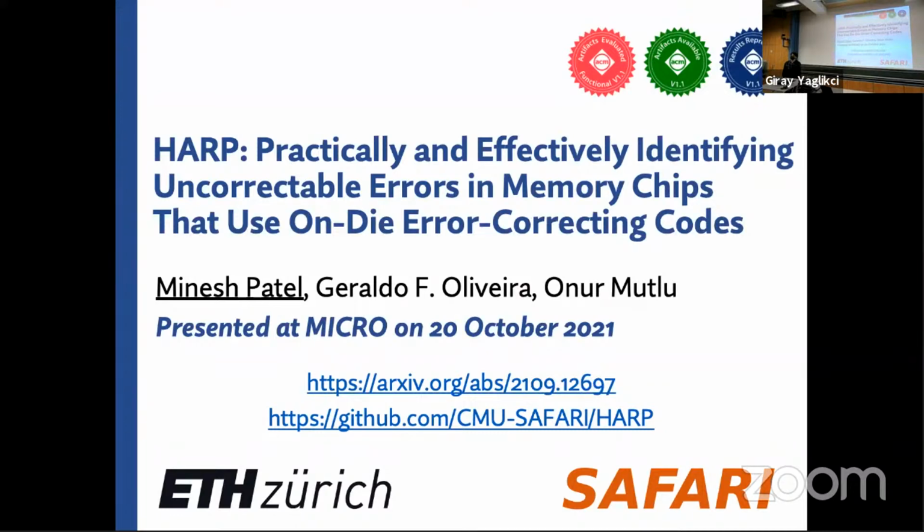in industry. And I think the results of, let's say, a BlockHammer kind of shows that also, right? We don't see any workload that, let's say, loses a lot of performance. And that kind of shows that these workloads are probably very, very rare. But there's no guarantee that they don't exist, and there might be workloads that actually, especially when technology scales and the RowHammer threshold reduces, there might be benign workloads that get close to inducing these bit flips.